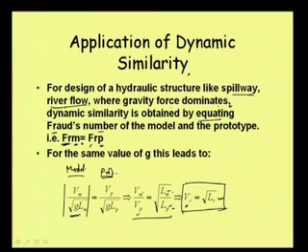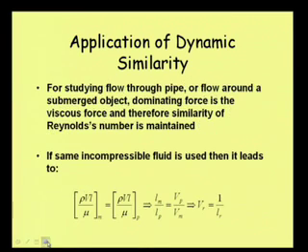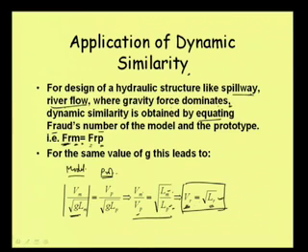But if we make the velocity ratio equal to the root of our length ratio, here you can refer to the slide, and then if we are maintaining that ratio of velocity, then this model study can give us results maintaining Froude number similarity. That means it is a dynamically similar model. Well, now let us see another case. So, we need to keep this point that Vr is equal to root over Lr when we are talking about Froude number similarity.